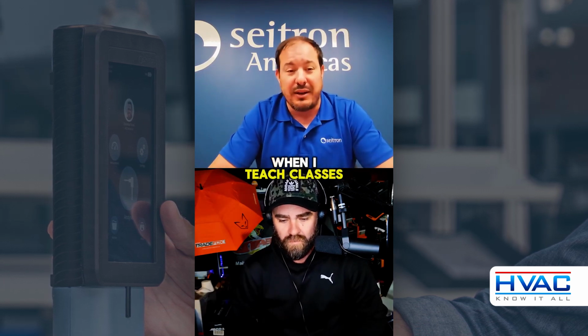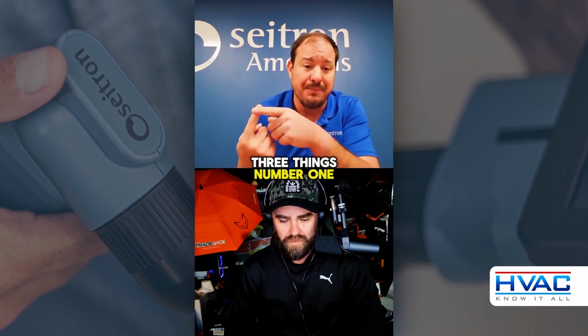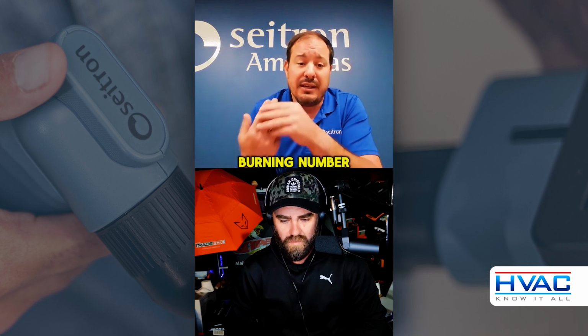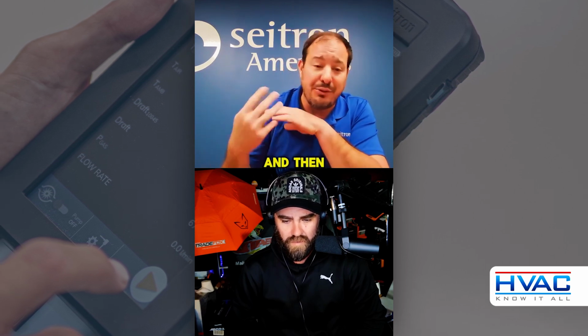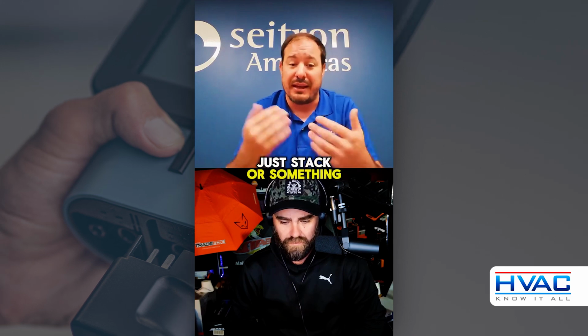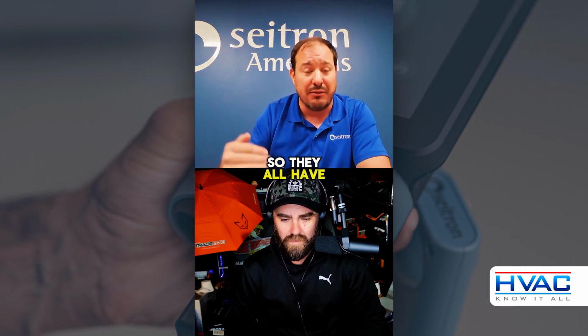Yeah, absolutely. So what guys don't understand, when I teach classes, and I go through how combustion efficiency on every analyzer is actually done, is by variations of three things. Number one, your fuel. It needs to know what you're burning. Number two, it takes the oxygen measurement and calculates CO2 based on the fuel you told it. And then the third part is actually delta T. It's not one temperature or another. Sometimes guys think it's just stack or something. I go, all those readings on your analyzer actually mean something, right? So they all have a meaning.